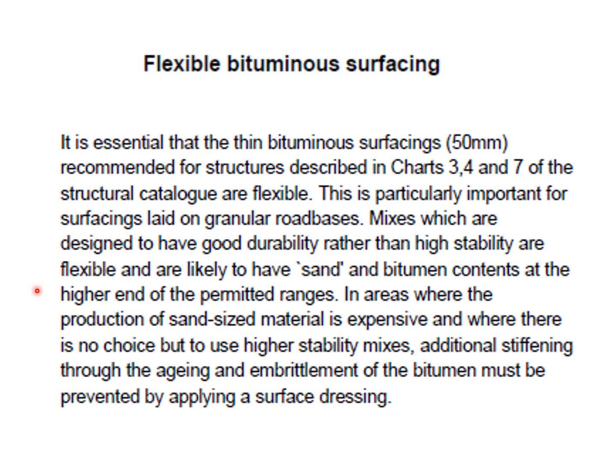Yes. In areas where the production of sand-sized material is expensive and where there is no choice but to use higher stability mixes, additional stiffening through the aging and embrittlement of the bitumen must be prevented by applying a surface dressing. So far we have discussed the 2 options, surface dressing and the option of the flexible bituminous surfacing.